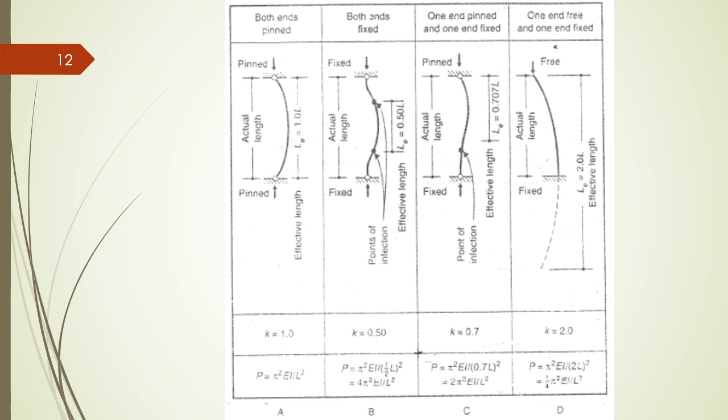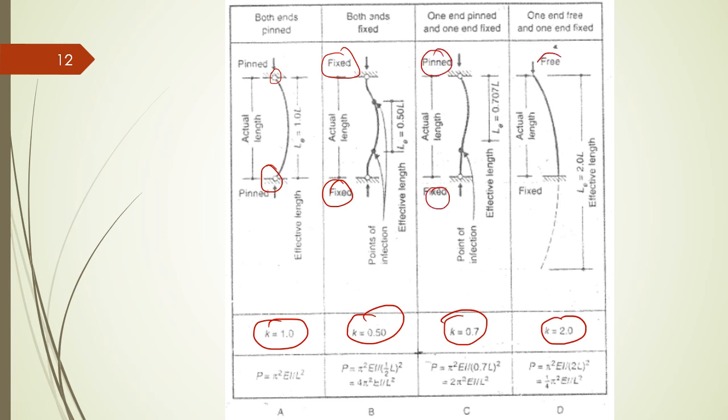This is similar to what you will have covered in our strength of materials course, where you have to find K, or the buckling length of different struts, which will be affected by the end conditions, whether it was pinned on the top and the bottom, whether it was fixed, whether one side was pinned or one side was fixed, whether it was just a cantilever with one side fixed and the other side free. So depending on the end conditions, that will affect our buckling length.